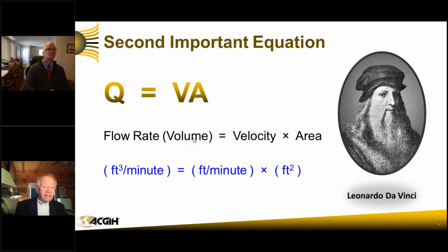It is not a volume. It says volume here because that's what everybody calls it. It is a volume over time. So it's a volumetric flow rate. And I don't care if you use volume because that's what people talk about, but as long as you understand that it is a flow rate, a volumetric flow over time, cubic feet per minute. And if you think about it, feet per minute times feet times feet is feet times feet times feet per minute, also known as cubic feet per minute. That allows us to keep that straight.